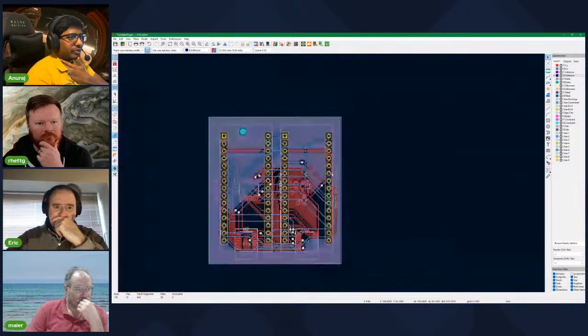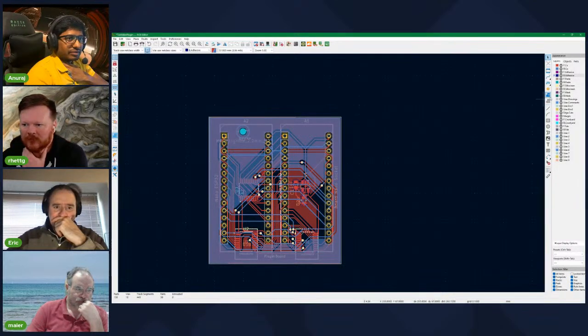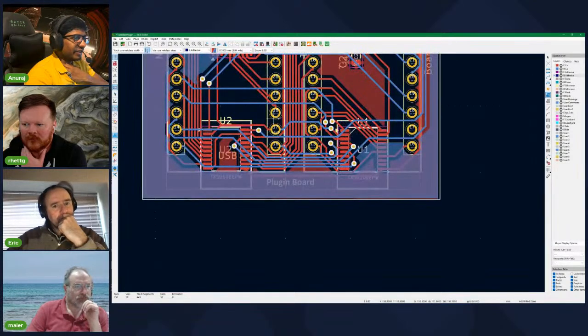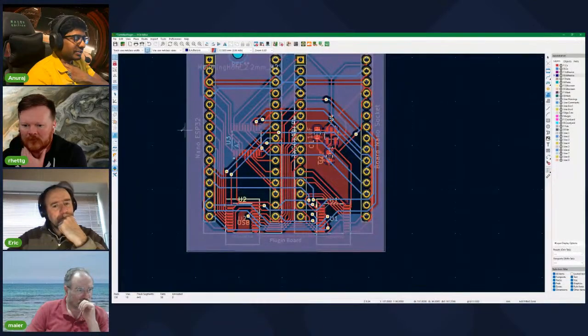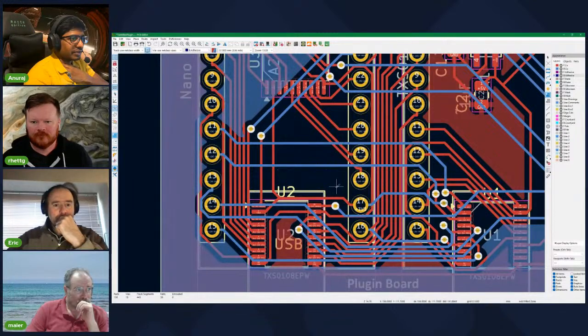Generally what you do is fill all the empty spaces with ground planes or some voltage planes. This is a fill zone. What I did was use a fill zone, put in the entire board dimensions, and fill the entire board with ground plane on top and bottom. Once you have put the polygons inside, it will automatically fill all the empty zones. I think there are some tolerance limits for that too.